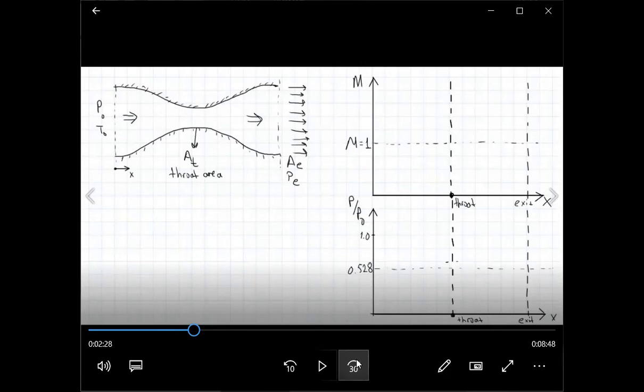The flow is moving towards the exit faster than the speed of sound everywhere inside the divergent part. So anything that you do at the exit, that information will never reach anywhere upstream. So you can never change it. The nozzle is basically locked aerodynamically. Okay, thank you, sir.